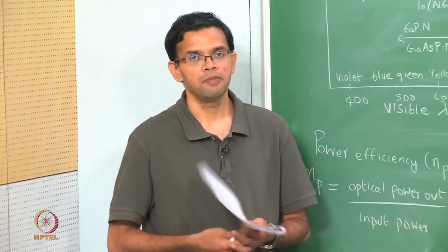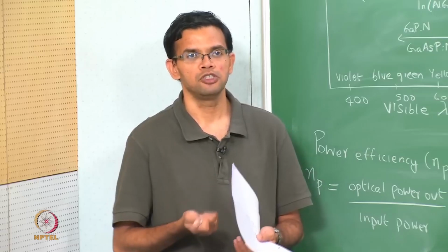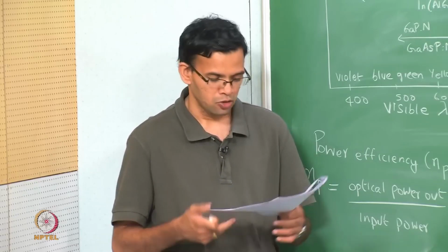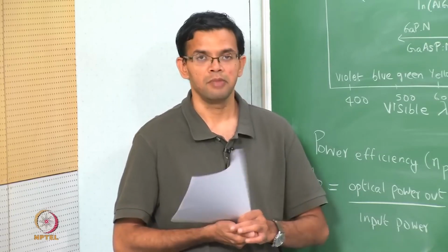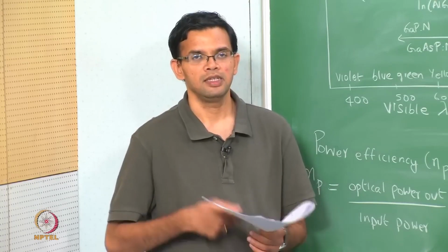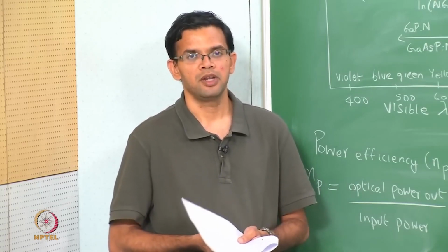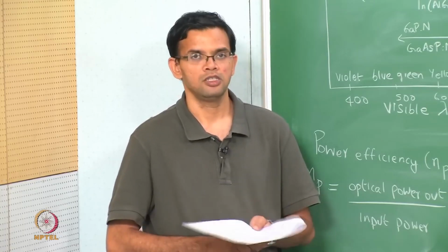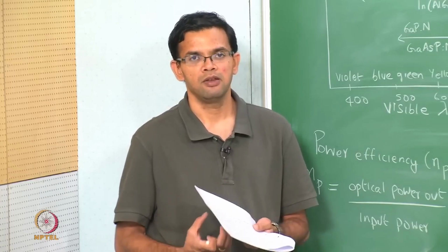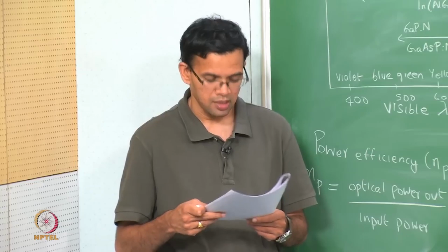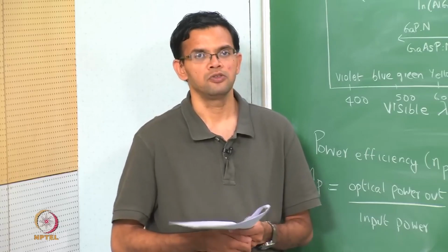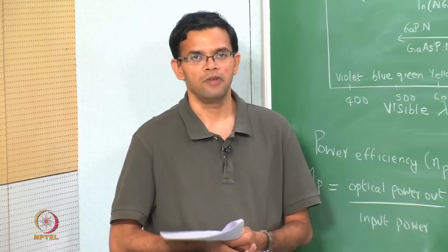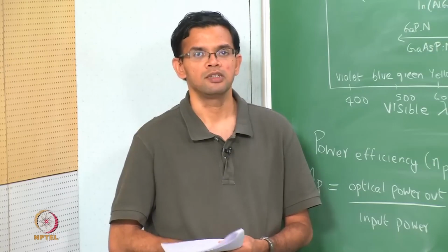There are different OLED materials that are available. Again you choose the material based upon the region of wavelength which you are interested in. OLEDs are useful mainly for display devices. They can easily be thermally evaporated onto a substrate, but one of the problems with OLEDs is of course the cost that is involved and the lifespan of these organic materials. Stability of the organic material is another issue, so water damage is an issue there, but OLEDs are another type of LEDs which are based upon organic materials.